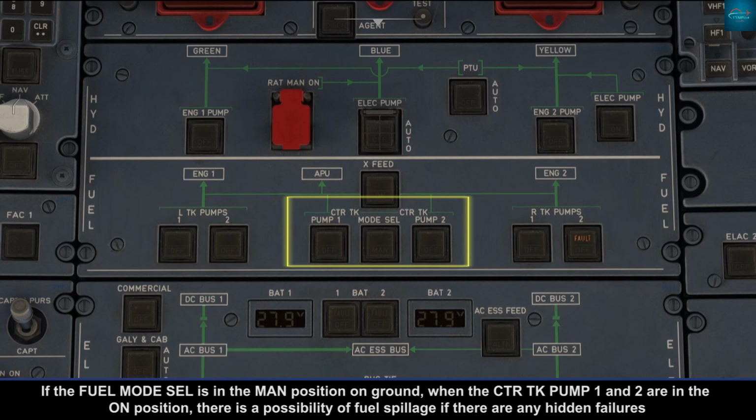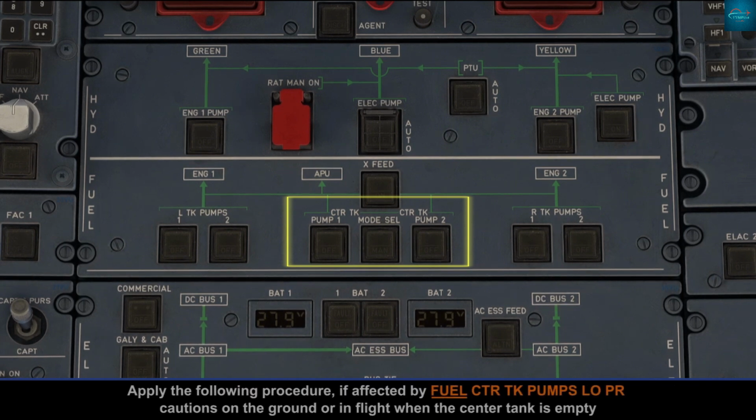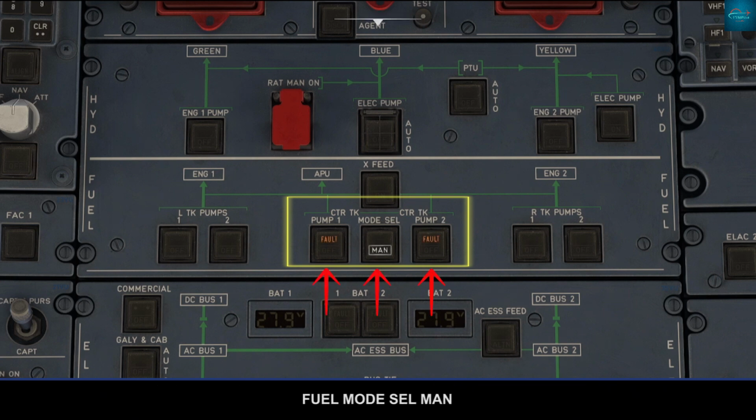If the fuel mode selector is in the manual position on the ground, when the center tank pump 1 and 2 are in the on position, there is a possibility of fuel spillage if there are any hidden failures. Apply the following procedure if affected by fuel center tank pumps low pressure cautions on the ground or in flight when the center tank is empty. Fuel mode selector, manual. Center tank pump 1 and 2, off.